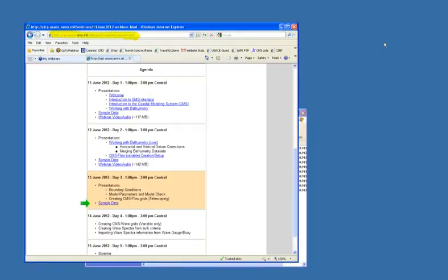For each refine point, you can right-click and choose Node Attributes and set a refine value, and this is the unit in meters based on that point. And so I'll do that for these 2 points I just added.